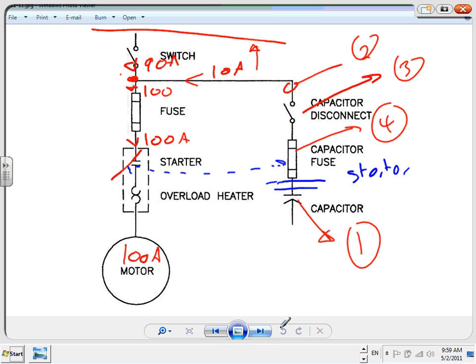So Camille, you're going to do, guys, in a second, one thing with Chad. You're going to size these four things for a capacitor. That's what we are required to find: the size of a capacitor. And Brooke, since we're designers, we always talk about wires, disconnect and the fuse, right? Like a motor. Remember how we did with a motor, guys? We always find the conductor that feeds it, the overcurrent protection device for it, and the disconnect for it. And in this case, we need to find the actual size of the capacitor. Any question, guys, about this?